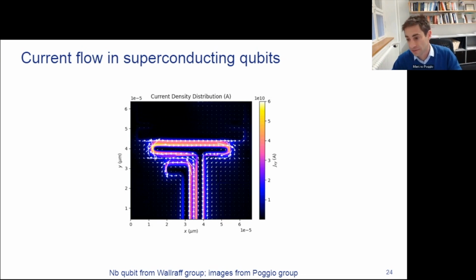For the diamond sensors that I showed, I'm not aware of them working in liquid, but I don't see any reason why they shouldn't be able to. They can work in ambient conditions also without vacuum. Certainly the sensitivity may not be as good as you would have at low temperature. And the MFM, of course, does. So standard MFM can work in liquid and in ambient conditions. Nanowire MFM hasn't been shown to work under those conditions, but in principle, with the right sensors, this could also work. Certainly the sensitivities will be different. You will have much more dissipation. You won't be limited by Brownian motion of the sensor anymore, but you'll probably be limited by effects of the liquid environment. But it should be in principle possible.